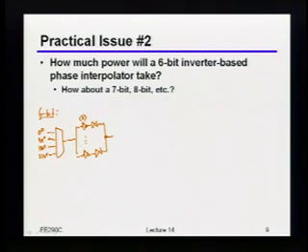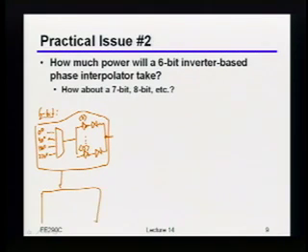So it would go conceptually from 0 to 15. And then, of course, just because I'm lazy, you'd have the same block over here, and then you tie those 2 outputs together. And then, if you did it exactly this way, you'd have something like 32x minimum size inverters running at the clock rate in terms of power.